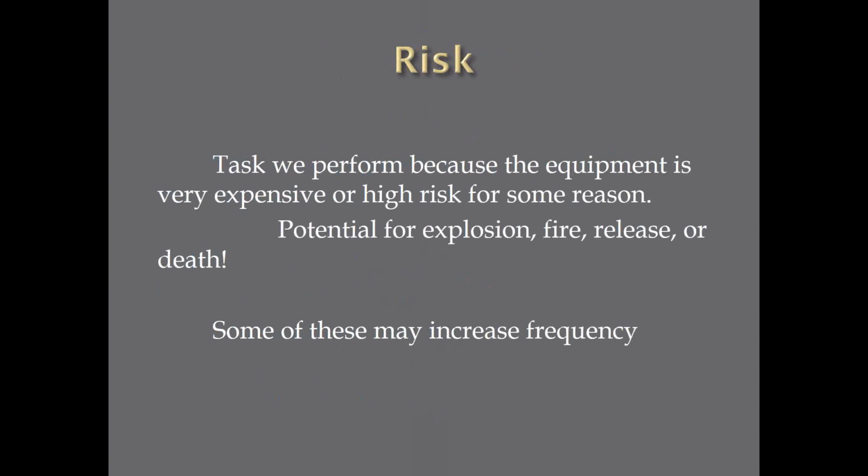But I asked the question, when was the thermography scheduled? Well, it was scheduled for a week or two from when they had the incident. And I said, how often are you doing the thermography? Once a year. Well, is that the right frequency for the risk?